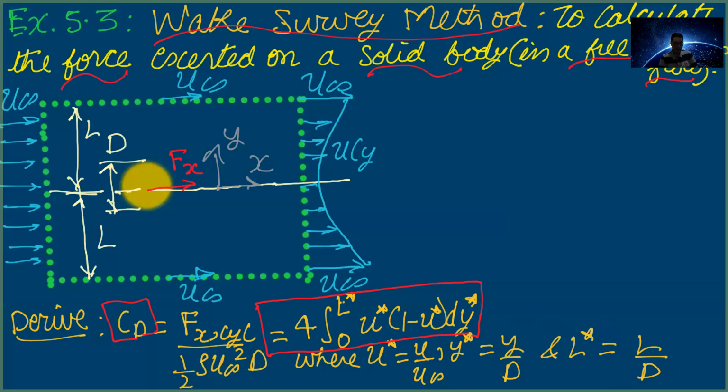So first let us obtain the reactive force acting on the control volume. To do that, we are interested in force only in the x direction, not in the y direction. So we'll calculate these x forces. Basically, here we are interested in the x momentum flow rate. In all this, I'll call this the left wall, this I'll call the right wall. The top and bottom together I'll call the side wall. So basically, we are interested in calculating the x momentum flow rate for the different walls.